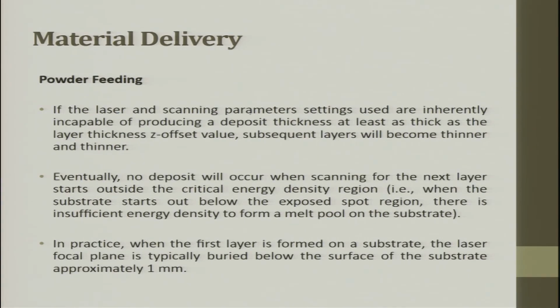To be noted, if the laser and scanning parameter settings used are inherently incapable of producing a deposit thickness at least as thick as the layer thickness Z offset value, subsequent layers will become thinner and thinner.